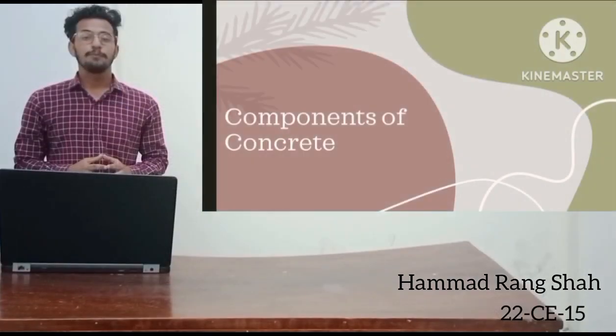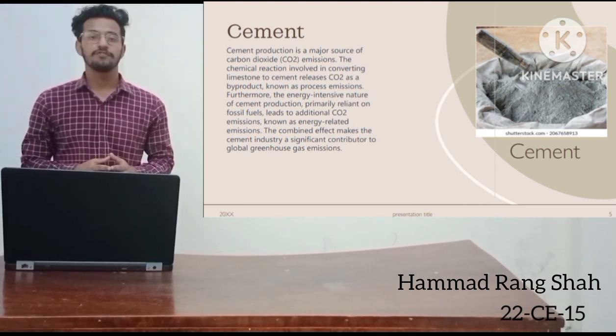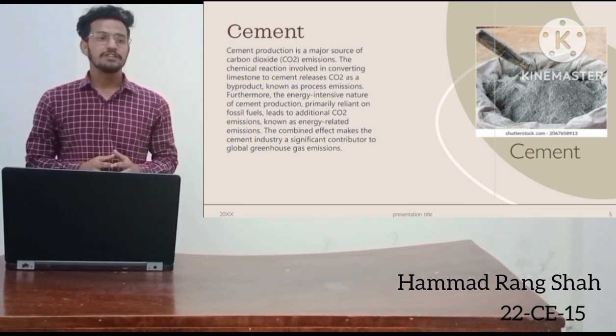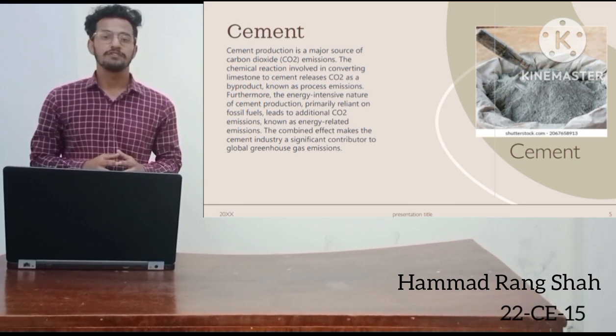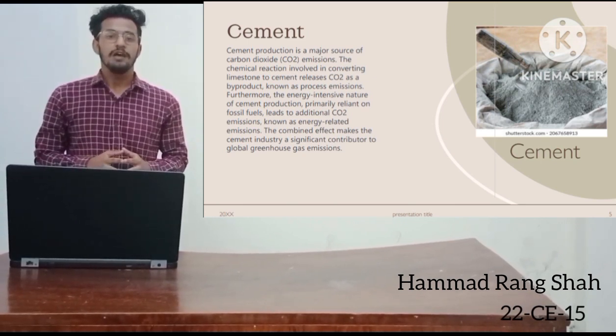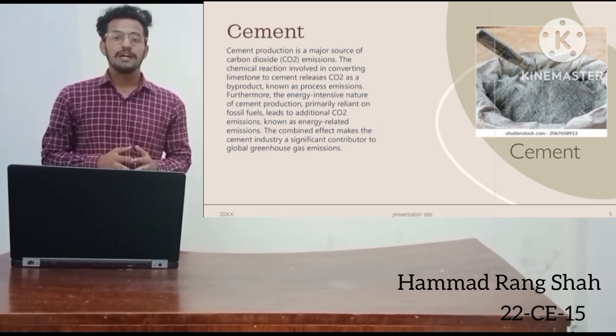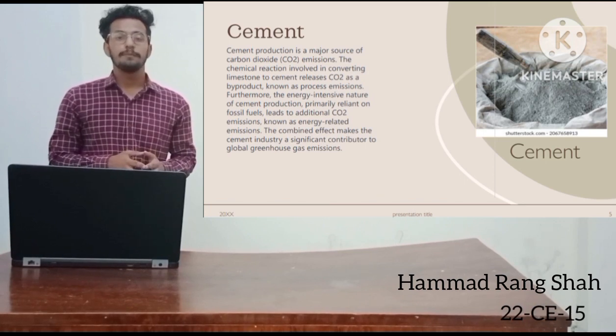And once we go to the components of concrete, we know that cement is the major component of concrete, and cement is the chief source of the emission of CO2. Because the cement industry is one of the main contributors to CO2 emission. About 8% of the total CO2 is due to the cement industries. So how is CO2 being emitted by cement industries? Because when limestone is converted into cement, it causes the emission of CO2.